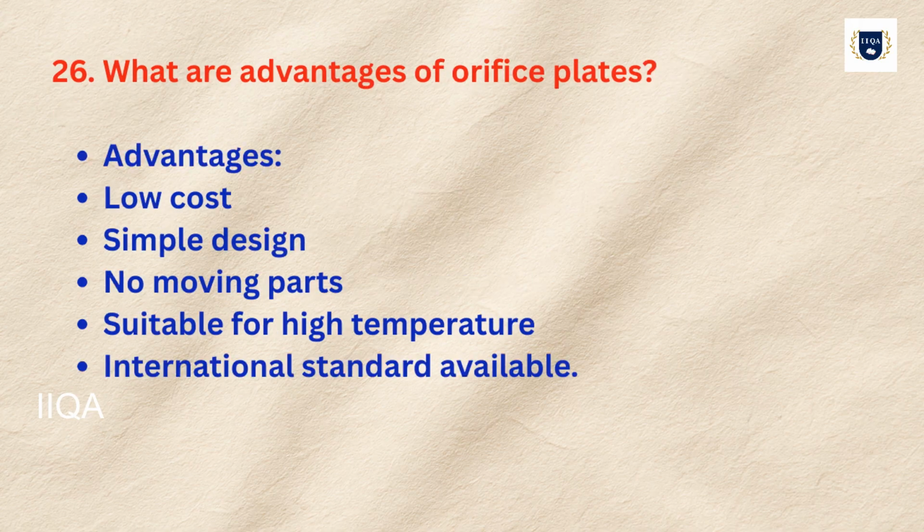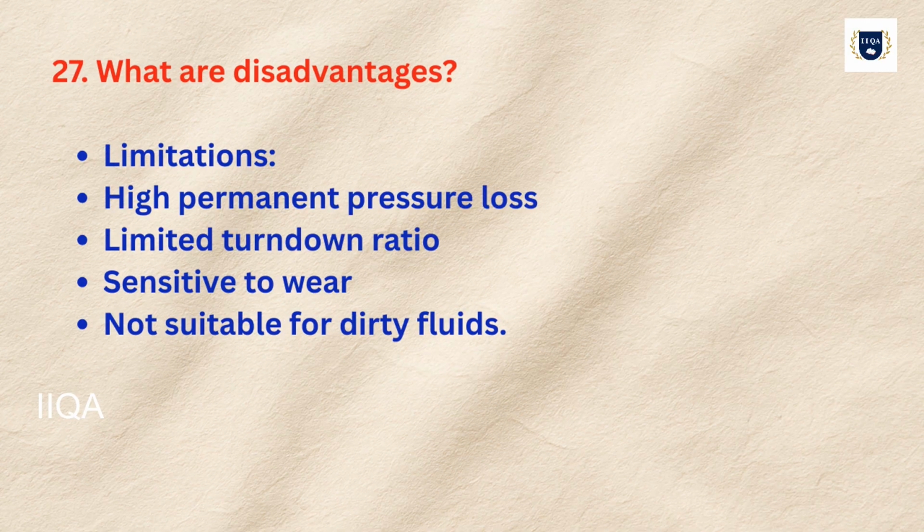What are advantages of orifice plates? Advantages: low cost, simple design, no moving parts, suitable for high temperature, international standard available. What are disadvantages? Limitations: high permanent pressure loss, limited turndown ratio, sensitive to wear, not suitable for dirty fluids.